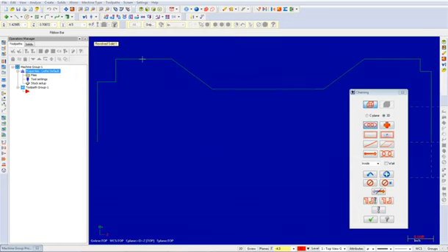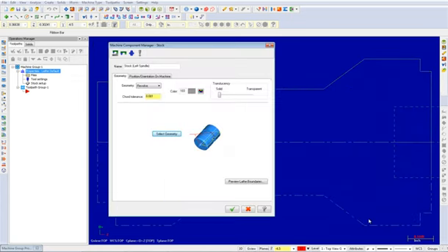The chaining dialog box has appeared. Leave the default settings in the dialog box and select Entity A as shown. Select the OK button to exit the chaining dialog box. You can now select the OK button to exit the stock setup page.